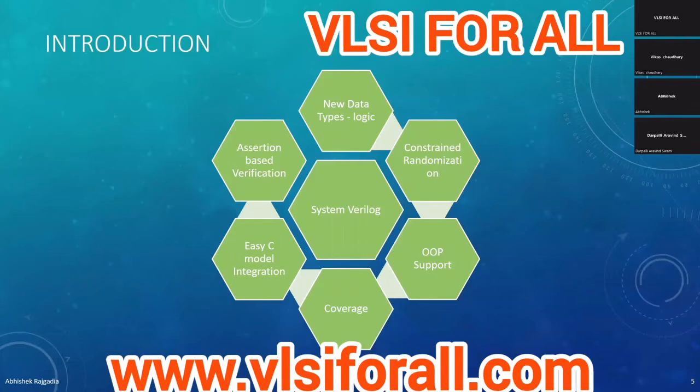Then there's easy C model integration. Basically, you can integrate a C model into your test bench. If there's a complex IP and you want to create a checker around it, let's say you are verifying a DDR, the connection from the memory controller to the DDR, you want to create a golden model of it. If you send something into the input and there's an output, how do you verify that the output is correct? You'll compare it with something, right?